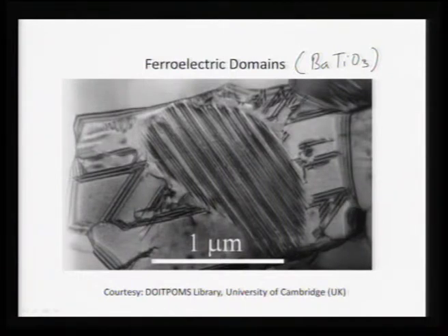This whole image is roughly 2 to 2.5 microns wide, and in these regions you can see these stripes, which are nothing but individual domains. You can observe these domains under a microscope. You can look at single crystals in optical microscopes just by doing polarized light microscopy. You can also do transmission electron microscopy, because you get strain contrast, this domain contrast, which helps you visualize domains of very fine size.